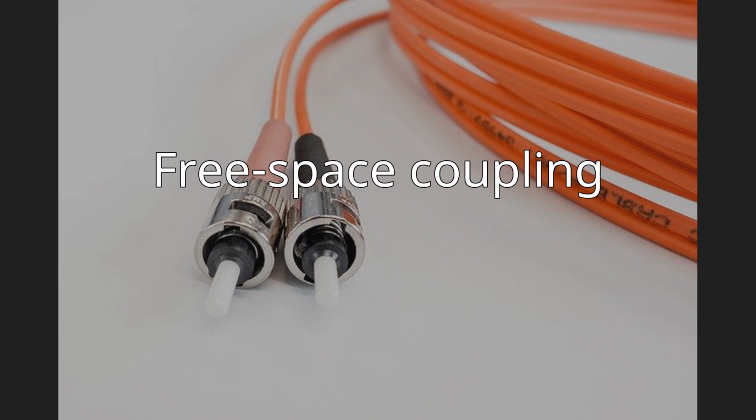With properly polished single-mode fibers, the emitted beam has an almost perfect Gaussian shape even in the far field if a good lens is used. The lens needs to be large enough to support the full numerical aperture of the fiber and must not introduce aberrations in the beam. Aspheric lenses are typically used.